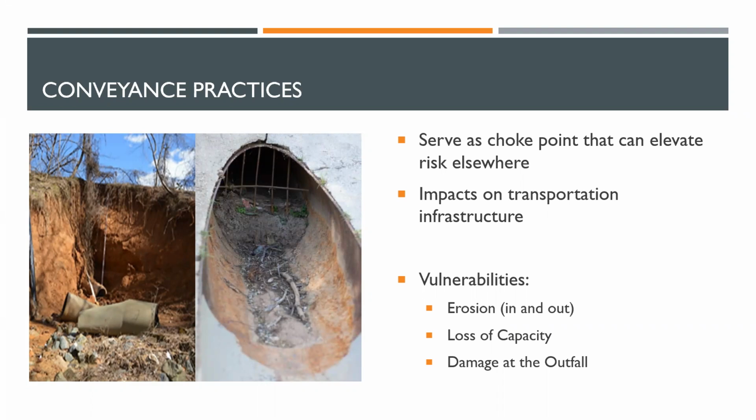We're also seeing some loss of capacity in these systems. That could be due to undersized piping based on the age of these conveyance networks. Because remember, a lot of these systems are the oldest within our system, maybe designed or built in the 1960s or before. So in those cases, maybe using precipitation data that's as old as 70 to 100 years at this point. They're also filling up, right, with either tidal backups in some of our lower lying areas, or by mobilized sediment, filling up the bottoms of those systems as the more intense events carry that sediment into our conveyance networks.